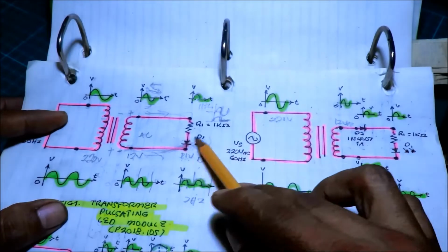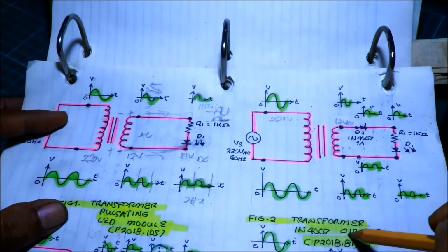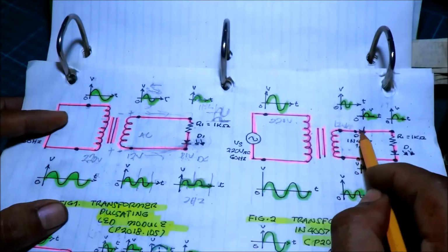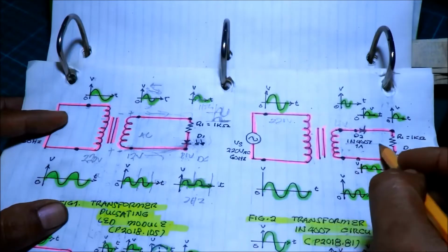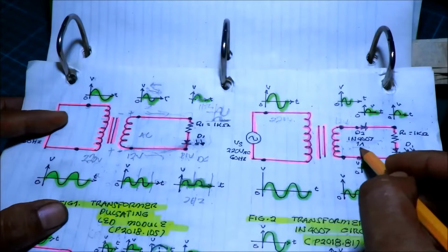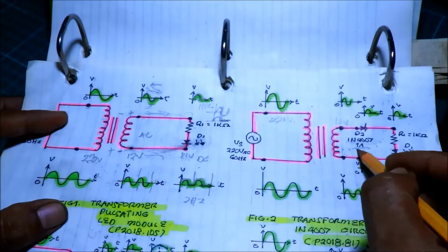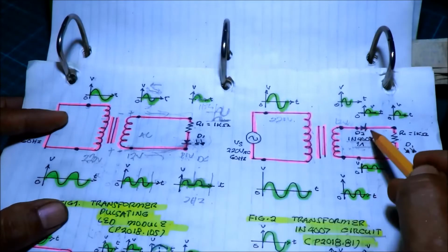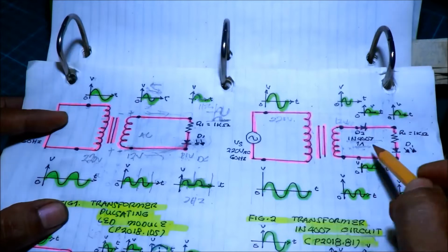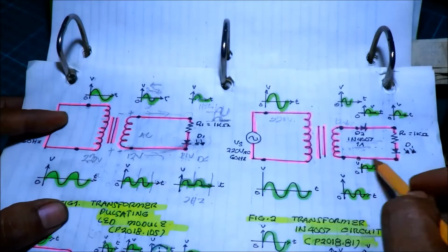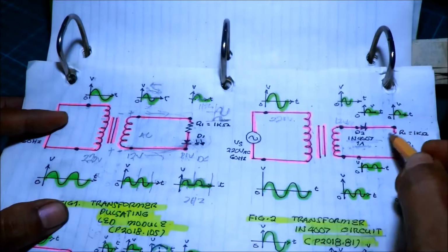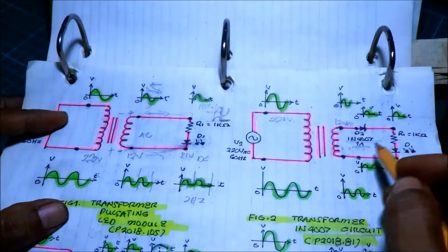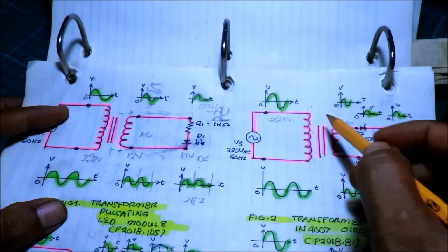what's the difference? Why did I construct this second project? The difference is I connected a new component here, and that is the 1N4007, 1 ampere. That is the current rating it can handle, 1 ampere. This diode now, 1N4007, will help to protect the LED from burning, due to the peak inverse voltage or the reversal direction of the wave. So let us now examine the current flows.